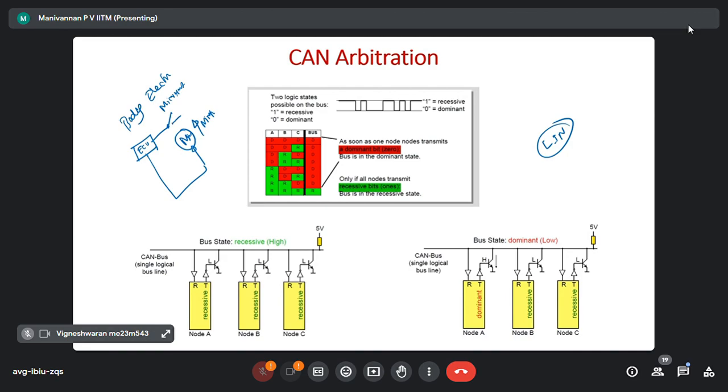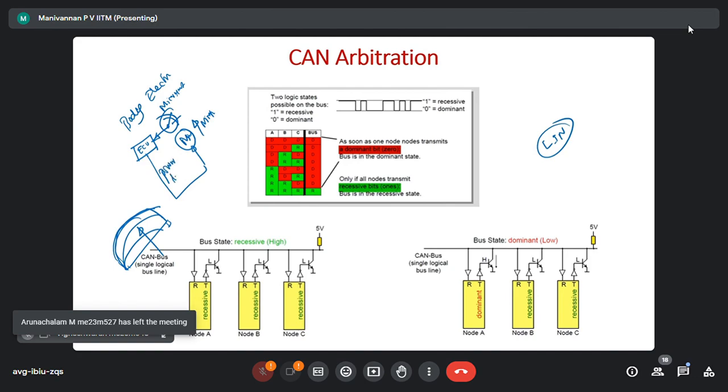Now how do you know that the glass has gone all the way up? If you have a window like this, the glass comes out, projecting and going up. When it reaches the top, there may be a micro switch, and the switch will be closed. Once it is closed, the ECU, which is watching the switch, will switch off the power to the motor. If the micro switch is open, the motor power stays on and the glass goes up.